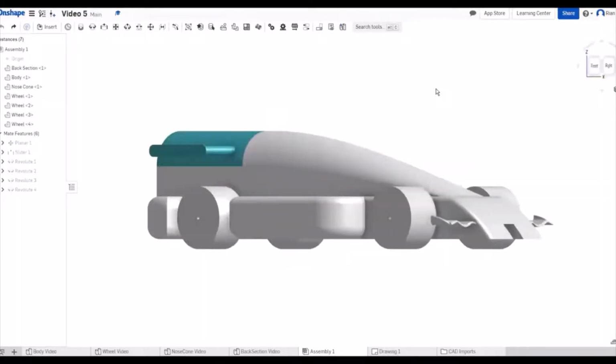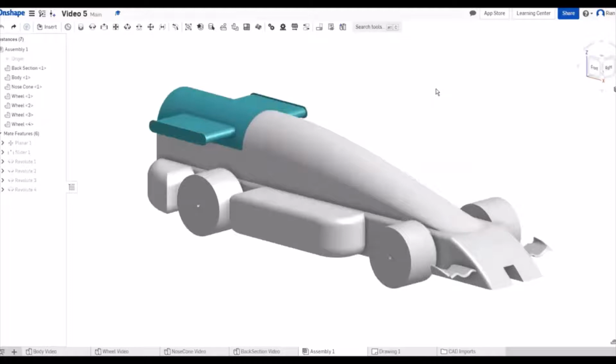How is this to make, Rian? So this was quite a simple shape to make, and it gives off a really good kind of effect for the amount of work put in. And if you want some more detail, watch our CAD tutorials that I voice over. So this body is very easy to make. It's just a couple of sketches and a loft, but the important bit is to make sure that the curve is really smooth at the back, so there's no turbulent air.